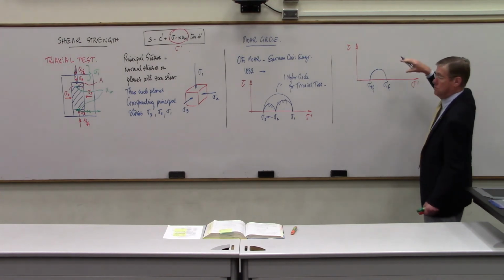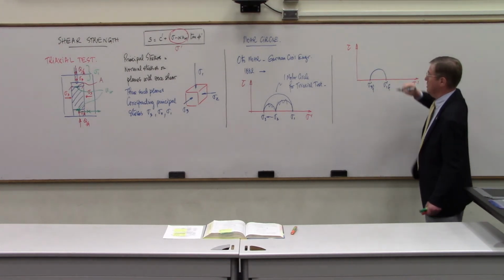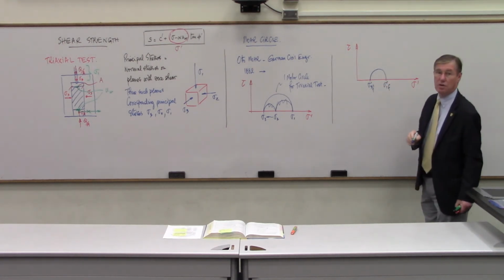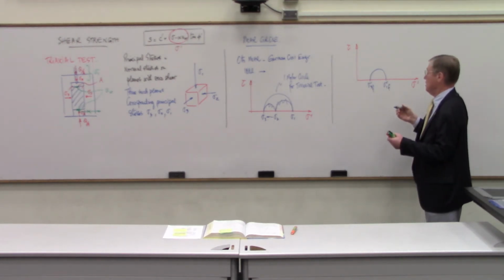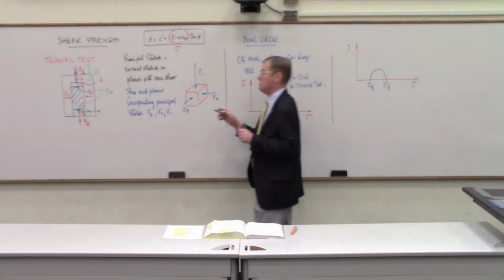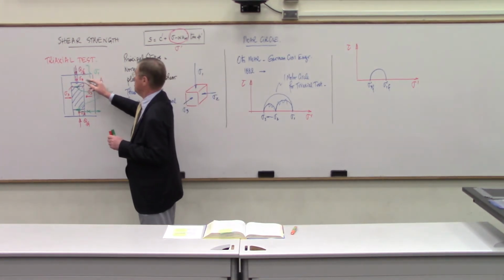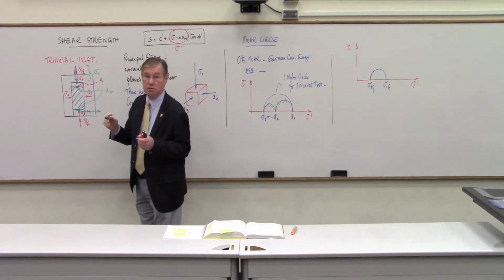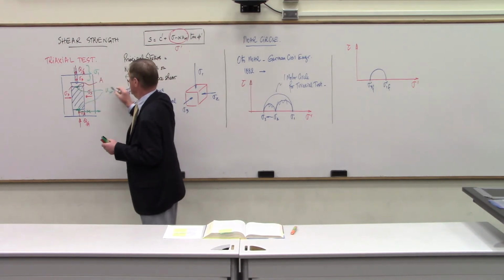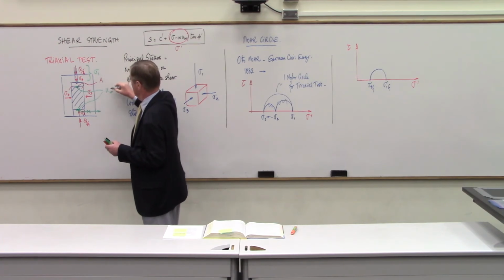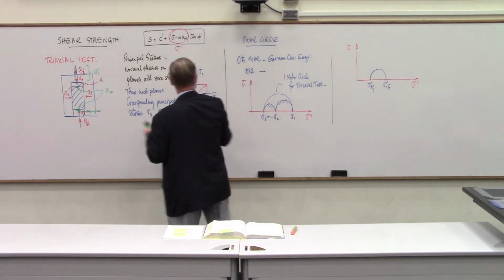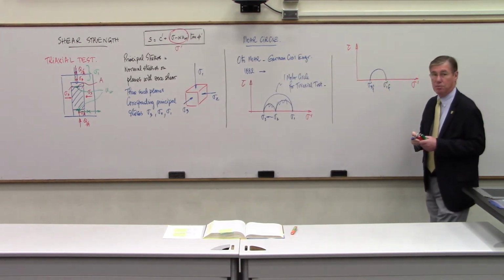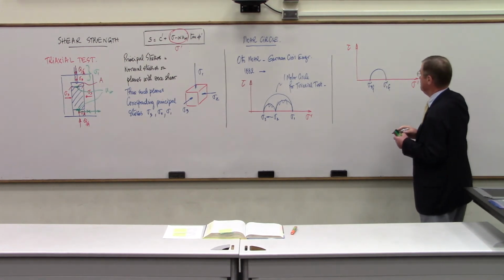You know the peak of the stress strain curve that I showed you, we take the peak of that curve and we determine what sigma prime 3 failure, sigma prime 1 failure is, and what we apply are total stresses. This Q over A plus sigma 3, that's a total stress. So if we don't do the test, drain so slowly that there's no water pressure, we're going to have to measure UW and then subtract: sigma 1 minus UW, sigma 3 minus UW with the alpha if we're in an unsaturated case. That's how we get these sigma prime 3 values, and we'll do a problem in a minute.